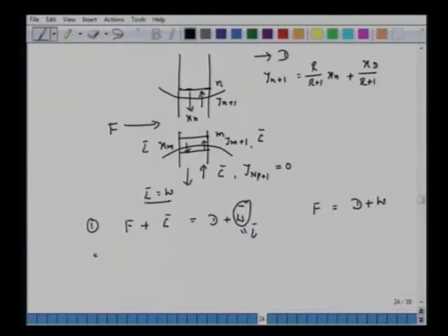Let's now make the species balance here. When we say operating line, either for the top column or for the bottom column, it is nothing but the species balance for that region. So when you make the balance for this region, now you have L bar Xm, the stream which enters this region or envelope which you have drawn here, plus G bar into Y NP plus 1, but that's 0.